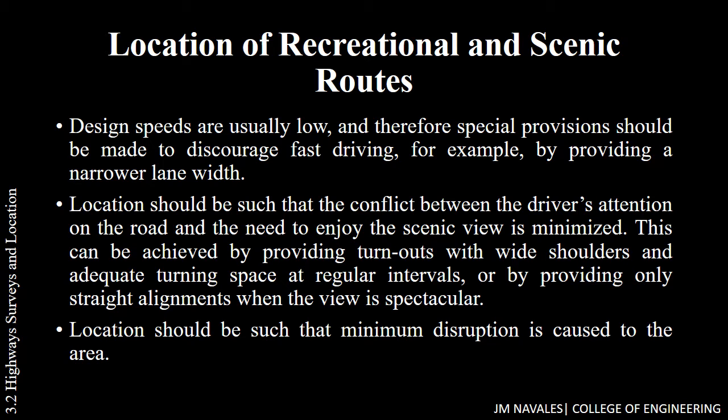Second, location should be such that the conflict between the driver's attention on the road and the need to enjoy the scenic view is minimized. This can be achieved by providing turnouts with wide shoulders and adequate turning space at regular intervals, or by providing only straight alignments when the view is spectacular. And last, location should be such that minimum disruption is caused.